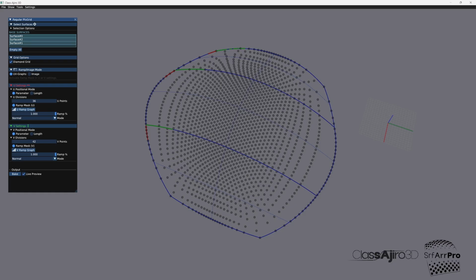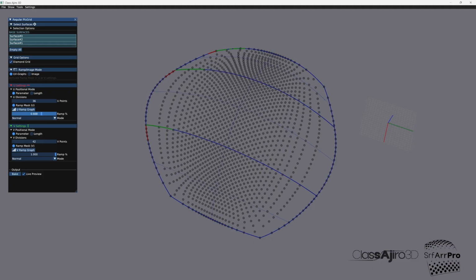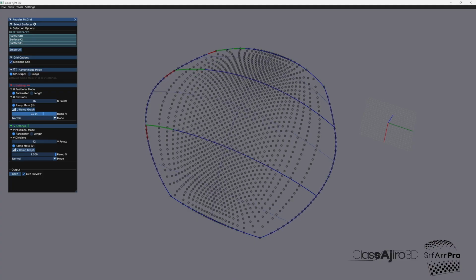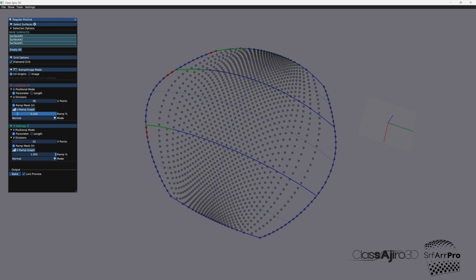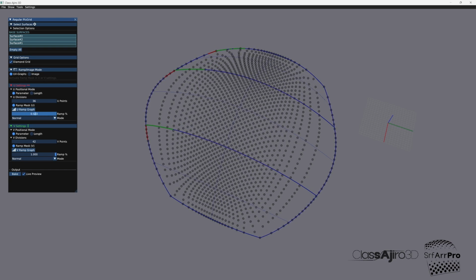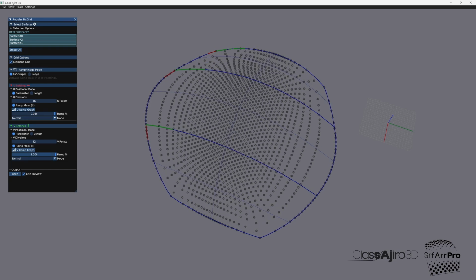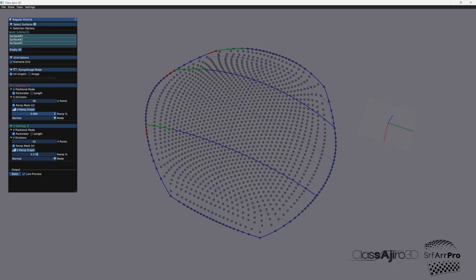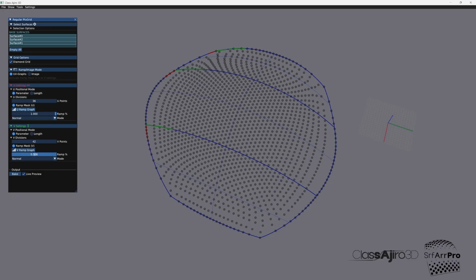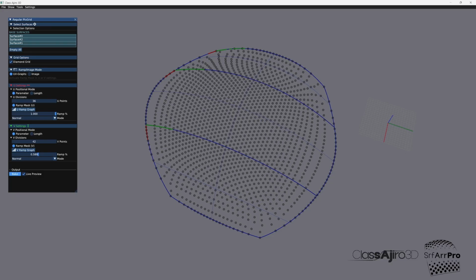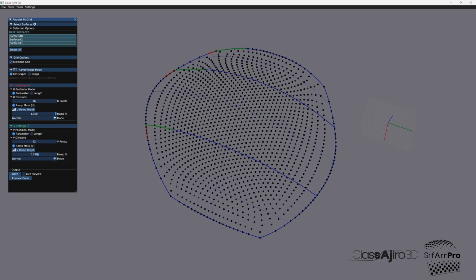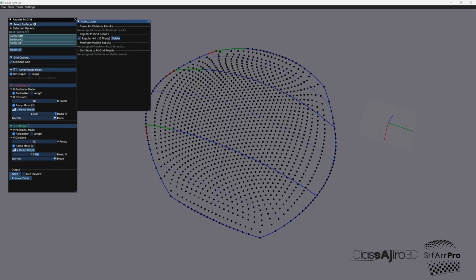Now, to give some extra controls, once you have found the right character of the curve, you can still work on the blend that the ramp had on the pattern. So there's a percentage, and you can decide how much of the ramp graph has effect on the pattern. So it's like a further control you can have on it. But once you're happy with anything you got, you can then bake it and get those points, which you will then have listed in the object lister. You can always hide them or even delete them.